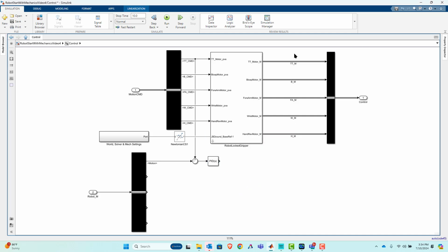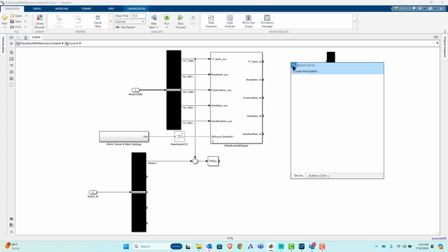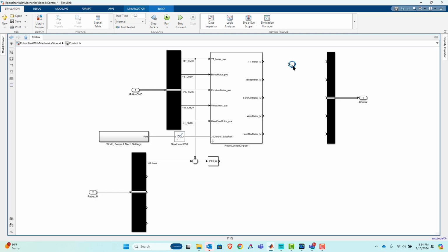And we'll add it so that the overall control for each of these axes will be the calculation of our mechanical model, what I'm calling the feed-forward control, the inverse mechanics, plus the feedback measurement. So I'll do a sum block up here too. I recall I fretted a little bit about just calling it control in the previous video, and I wanted to call it torques.